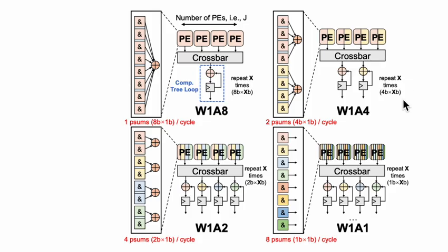So this figure illustrates the operation modes of BETA's configurable PE sequence. The PE sequence can adapt to different combinations of weight and activation precision. It uses two key techniques: data packing, which allows multiple multiplications to be combined into one PE output, and bit-serial traversal, which processes multi-bit activations sequentially when necessary.